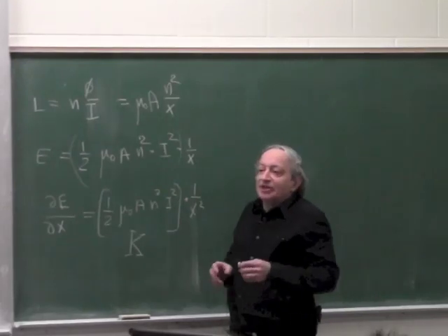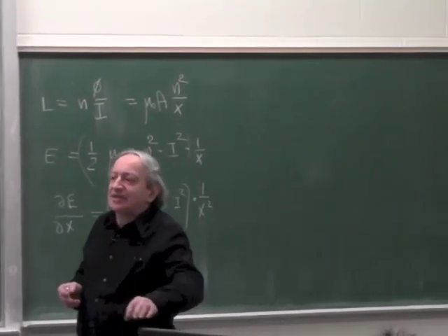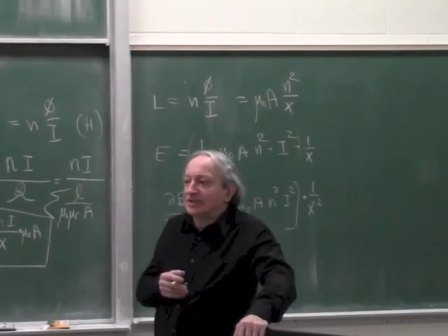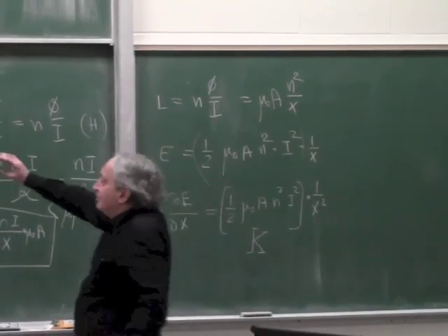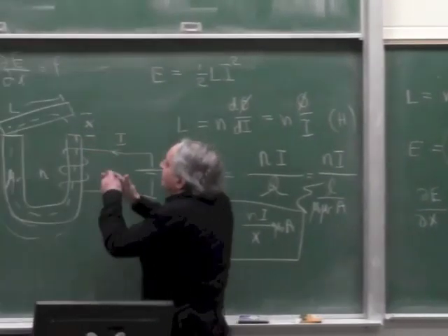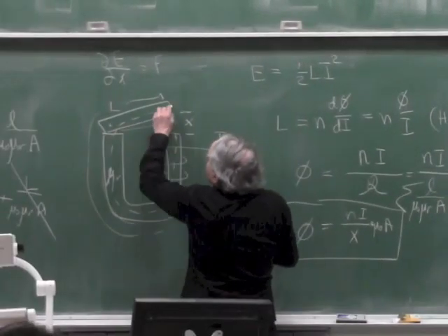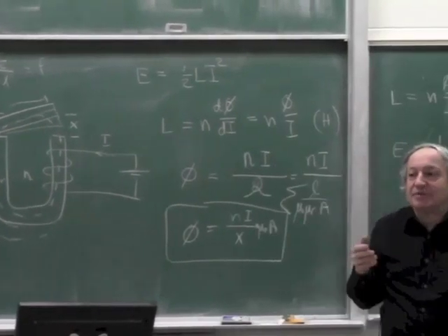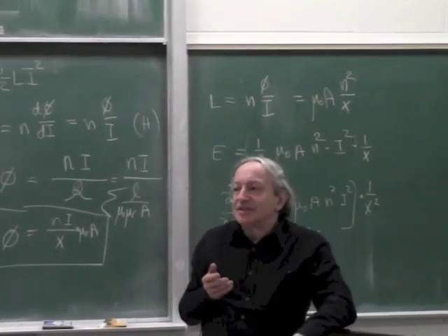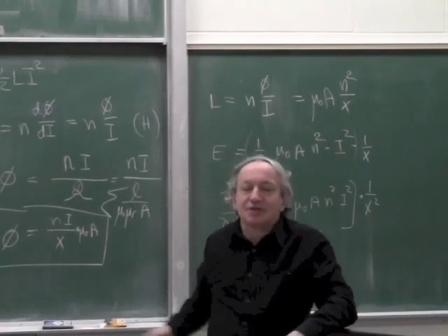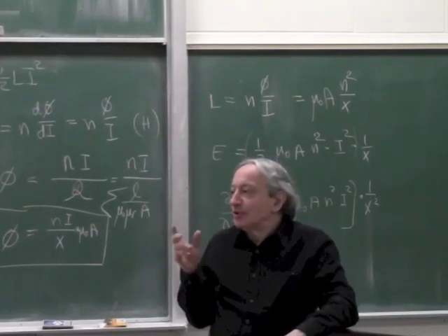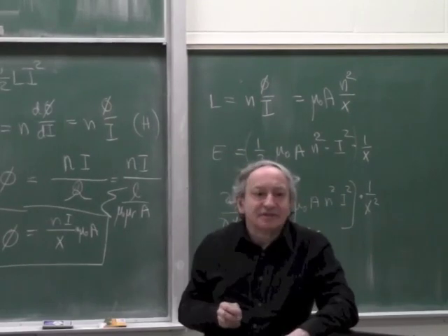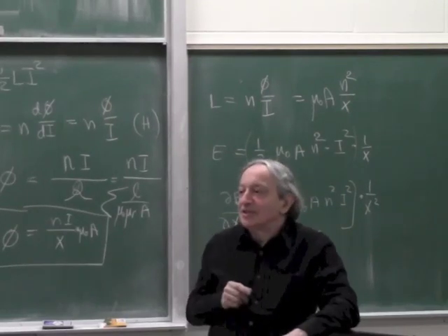Now, can somebody intuitively understand why it's not good when an actuator in a servo system is not linear, say with travel? What this means is that if x is half, the force will be 4 times, so the force will be nonlinear with travel. Now, why is that bad in the servo system? Because I'm closing the loop. All I'm trying to do is control position. So what's so bad if it's nonlinear with travel? That needs some understanding of servo systems.